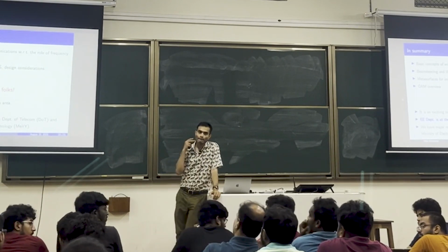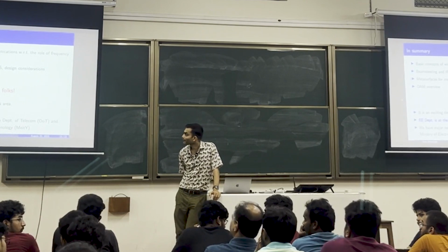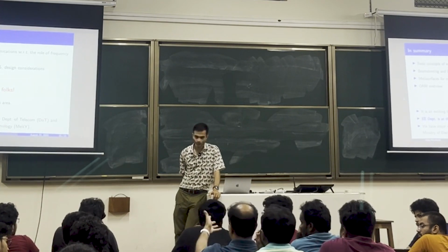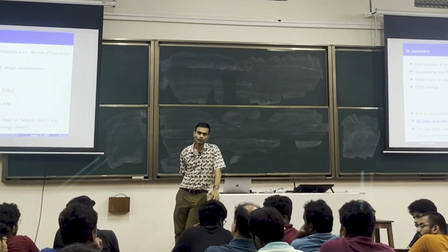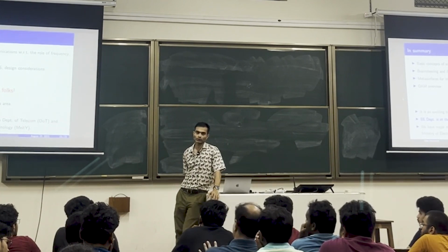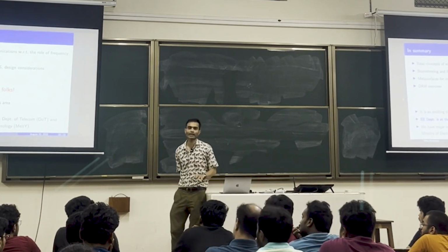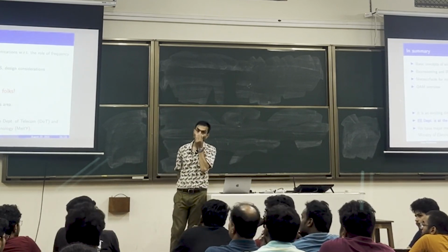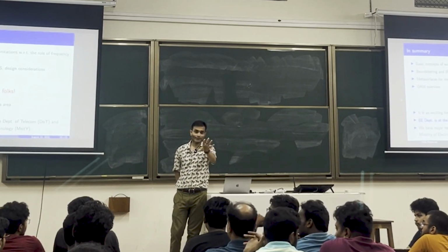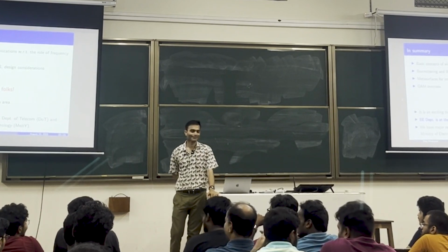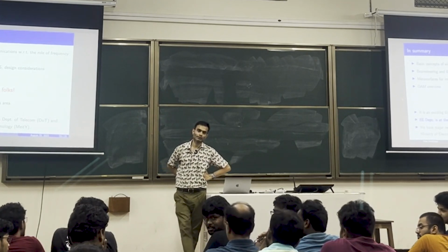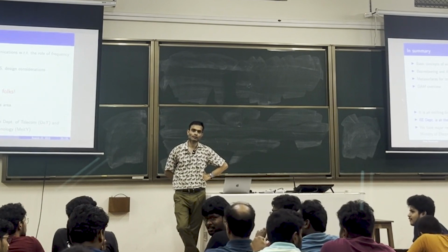I'd like to check on your assertion about IRS increasing capacity. I guess it increases diversity for sure. They add more paths, yeah. So it's not like a new antenna, right? So it doesn't give you more degrees. Well, it doesn't give you multiplexing. It's not multiplexing. There is more spatial diversity, is what is giving the improvement. You get better, probably better. Correct, but not more capacity. Yeah, I'm sure you're right. Your dependence of the probability of error on the SNR will be better. Yeah, it doesn't give you multiplexing.